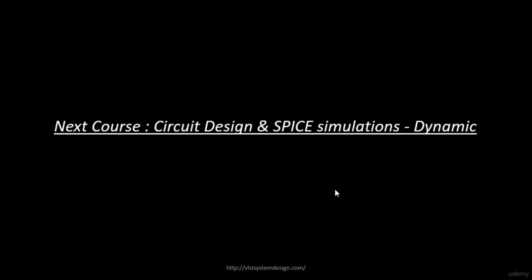In this particular course, we have been looking into all the static analysis, the static CMOS behavior. In the next course, we'll be looking into dynamic CMOS behavior. When I say dynamic, it's basically that the waveforms or the signals will vary with respect to time. For example, when we calculated the rise delay and fall delay for a CMOS inverter, that's the dynamic simulation. Wherever we were dealing with voltage levels, that was static DC simulation, at a given time t. Now the dynamic simulations will be a varying function of time t. The waveforms will vary with respect to time t, and that will be our prime focus in the next course on circuit design and spice simulations.